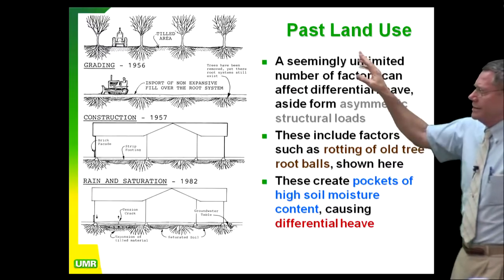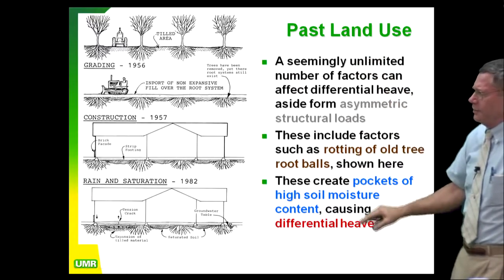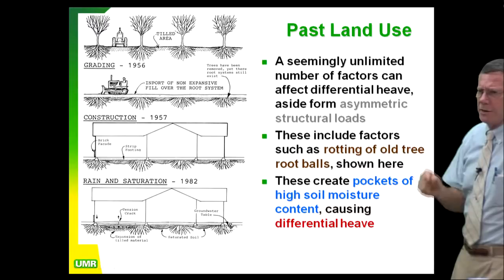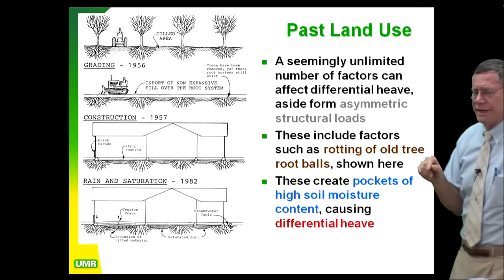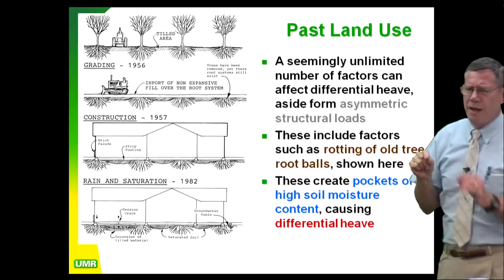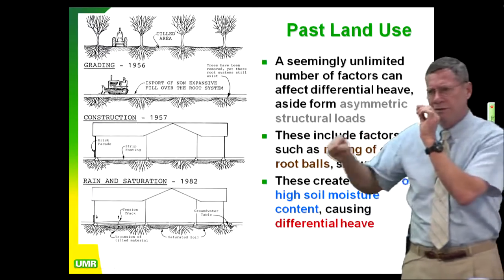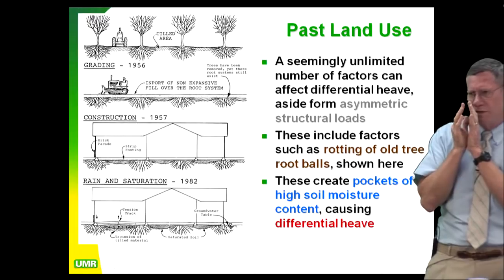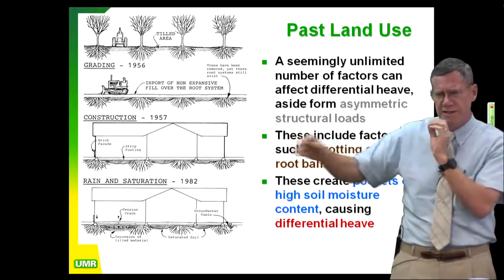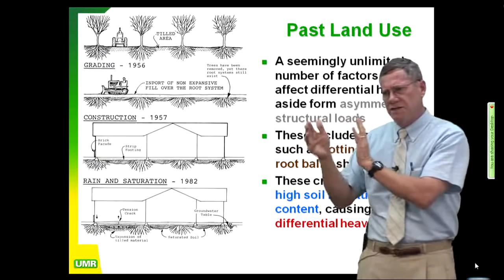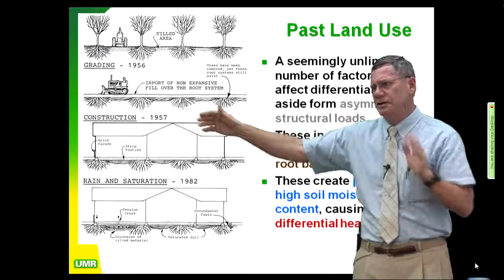And part of your homework is you look at as many air photos as you can find. Air photos are much more reliable than people's memories. You can interview people, but people tend to have a memory like a log spiral. They remember stuff really well that's in the recent past, and as you get farther and farther away into the past, their estimates of the times get worse and worse and less reliable.